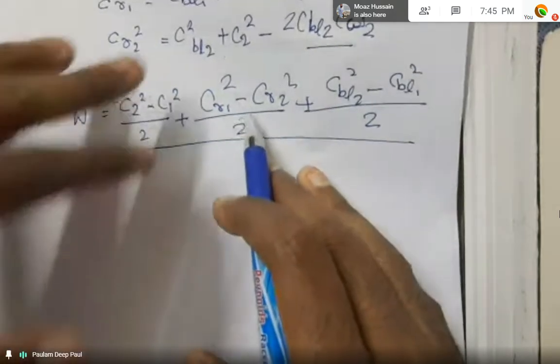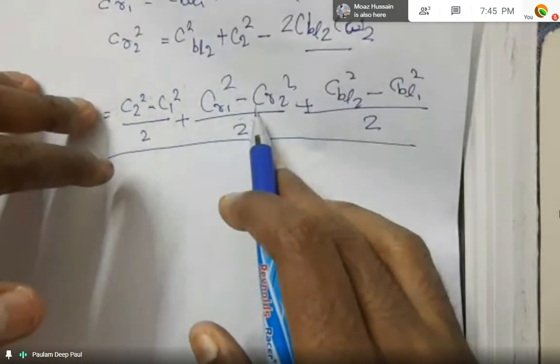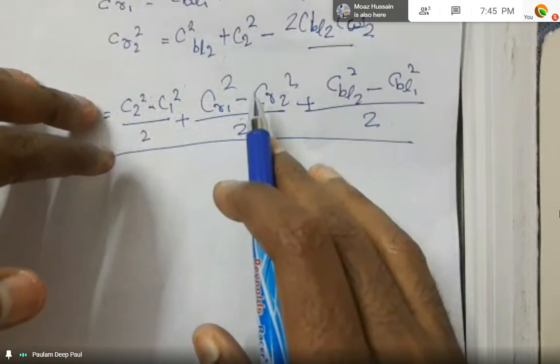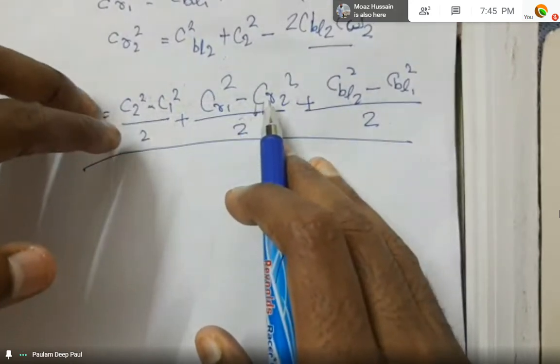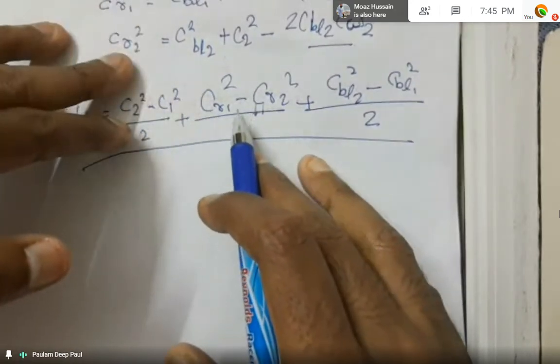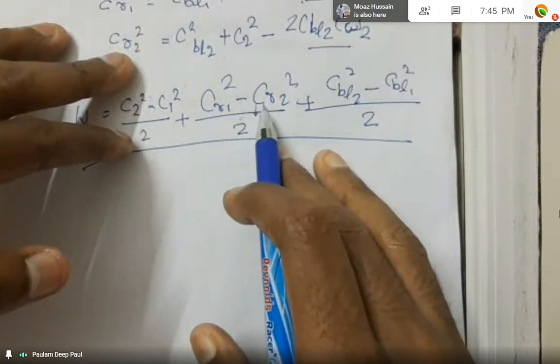The second term that we are dealing with shows the pressure rise in the impeller due to the diffusion action, as the relative velocity decreases from the inlet to the outlet.